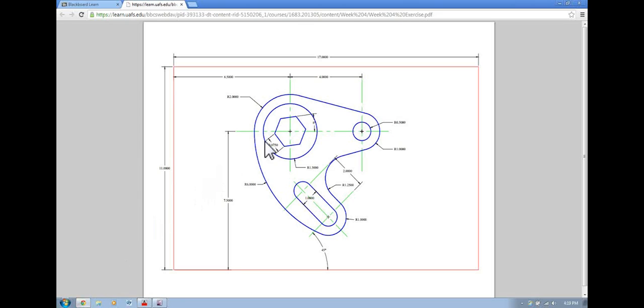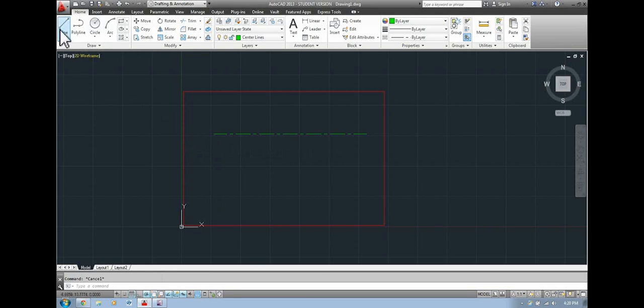Okay, so next I'm going to do these 2 vertical lines here. So we have a 6.5 inch offset from this rectangle to the center line, and a 4-inch offset from the center line to the next center line. Okay, so what I'm going to do, pull back into AutoCAD, do something very similar. I'm going to start here at this endpoint, come across 6.5 with object snap tracking, and then come straight down some arbitrary distance, okay? And now the 2 lines intersect.